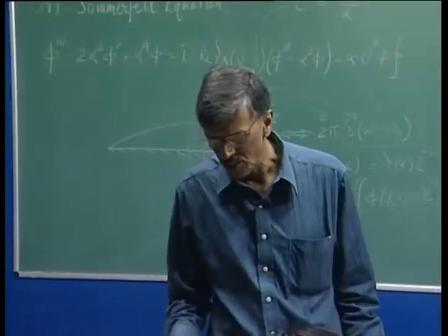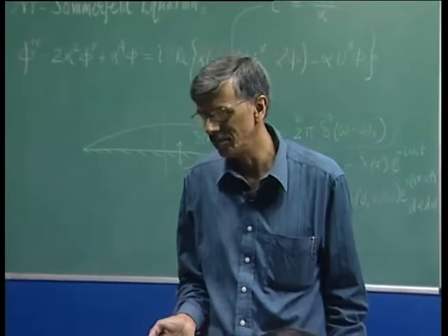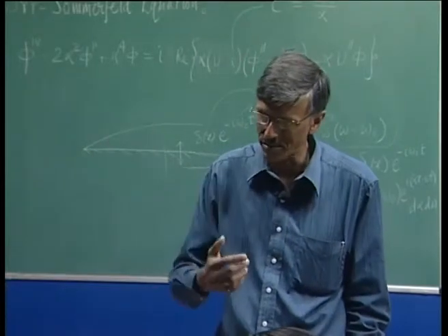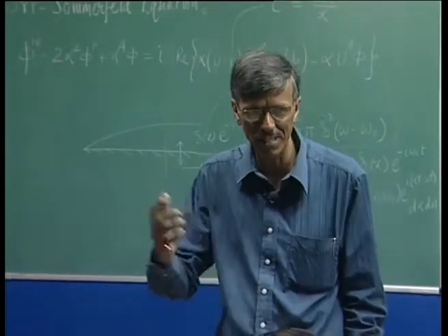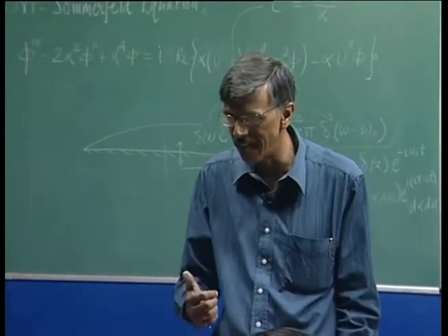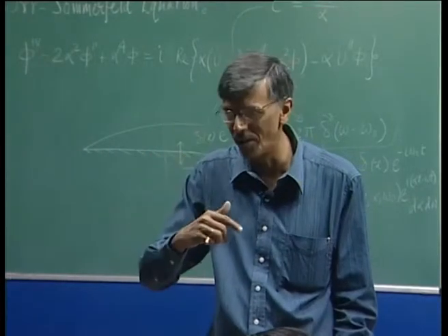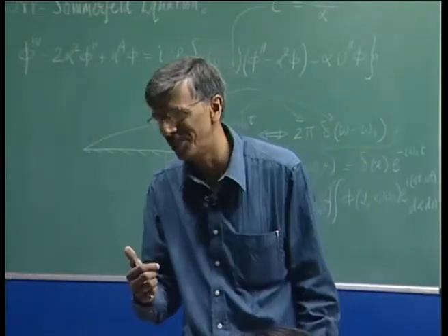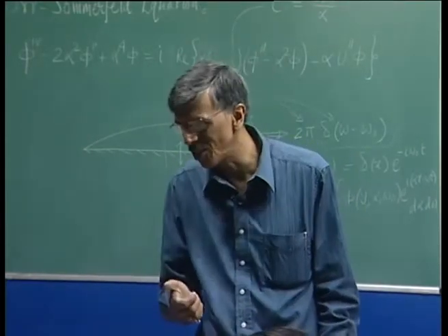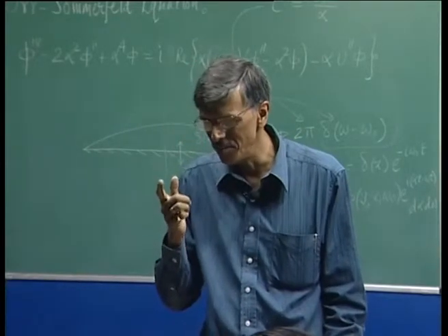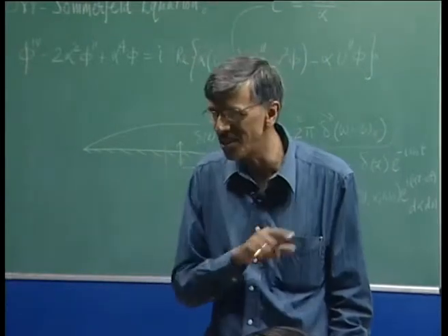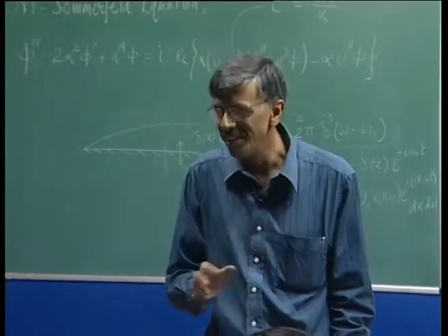For example, talk about this clear air turbulence. We have figured out that if an atmospheric convected vortex is approaching the aircraft wing, then a pilot can decide whether to go over it or below it, provided he knows the sign of the vortex. If you are talking about a vortex which is rotating counterclockwise, it would be very, very advisable for the pilot to duck under it, and then instead of destabilizing the flow, it will stabilize the flow.